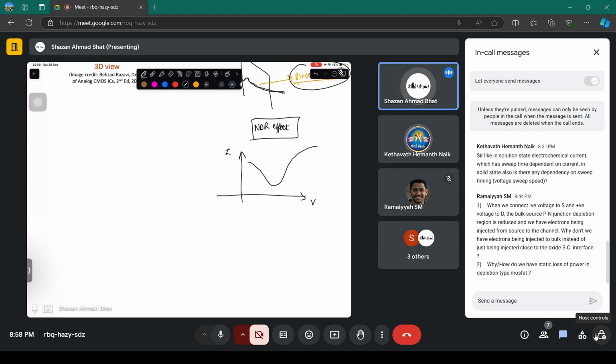In that small regime also we can use it for switching purposes. That is used in neuromorphic devices for switching, the negative differential resistance, where you have the current looking something like this when you turn it on, but when you turn it off, it's not able to follow its path, and it forms a resistive state. So you call that a high resistive and low resistive state, right?